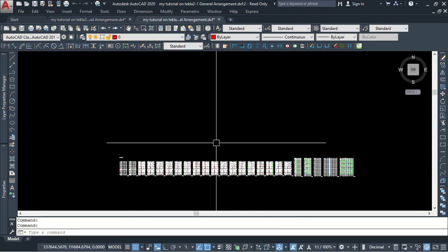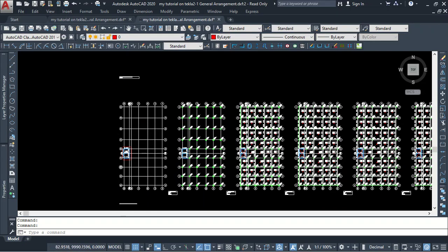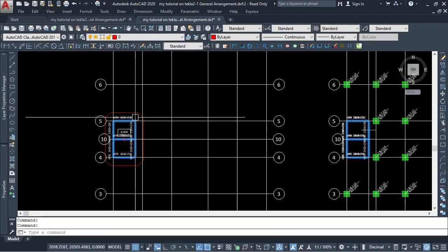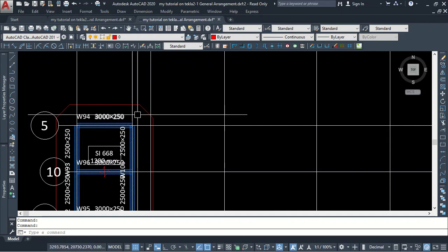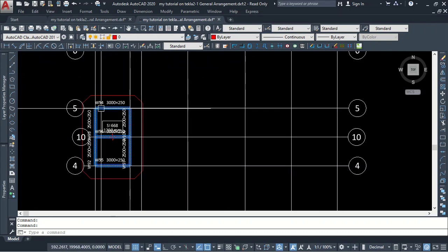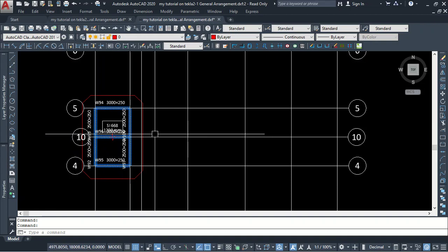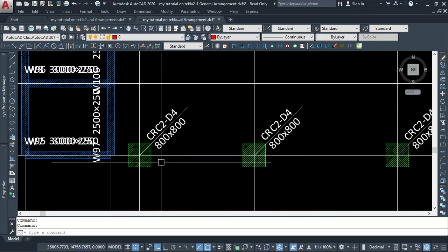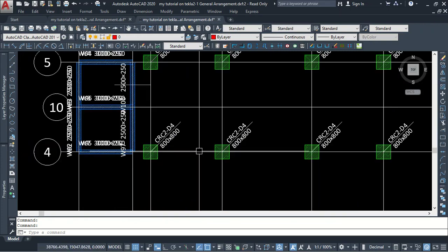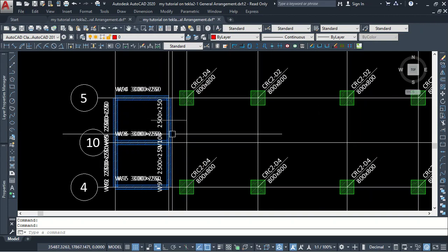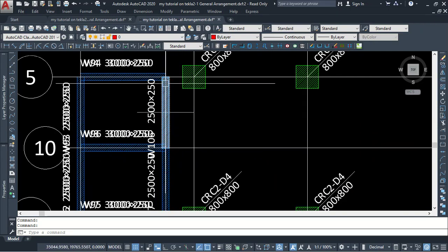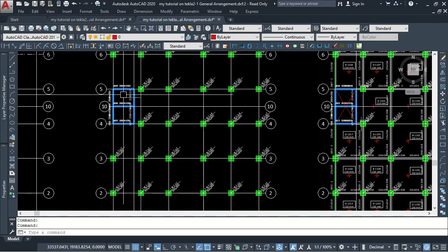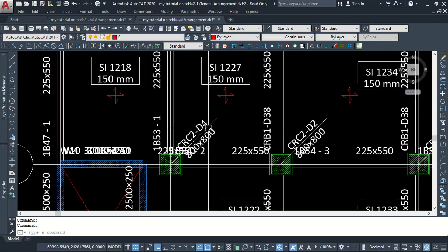All right, let's look at this one after the other. This is below the base, because my lift is below the base. It's a little below the base. They are not at the same level as the base. So this is the base. You can see the column sizes here. You can also see the dimension for the shear wall. The thickness is 250, and each of these bays is 2,500 mm. So you can quickly look at that.